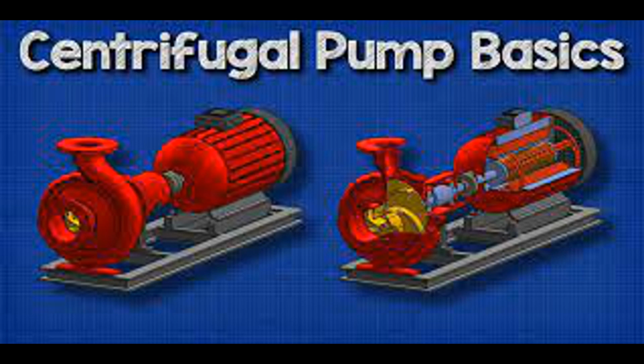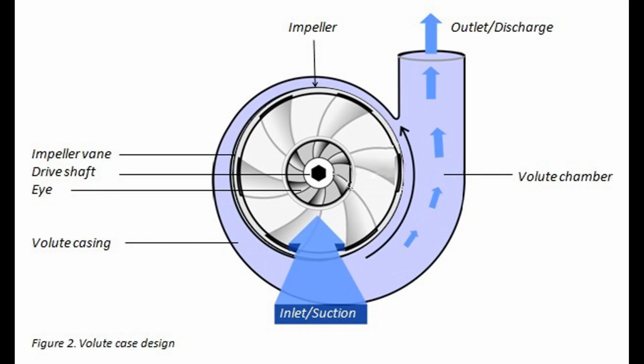Understanding the specific requirements of a pumping application is crucial for selecting the appropriate type of pump. Radial flow centrifugal pumps are well suited for applications where the emphasis is on developing higher pressures rather than large flow rates, making them valuable in scenarios such as industrial processes and water supply systems.